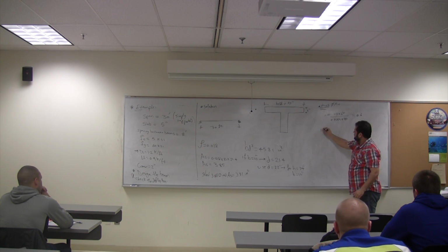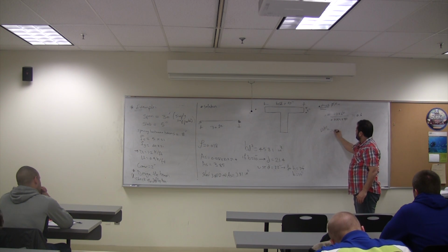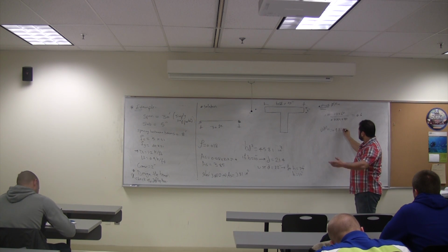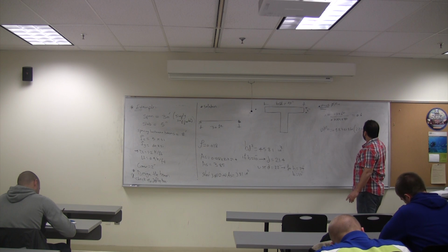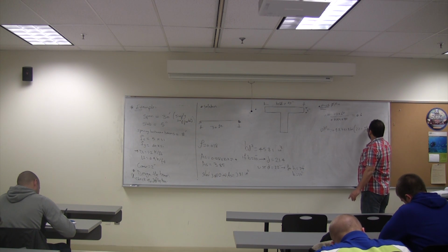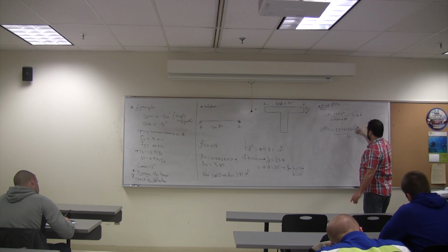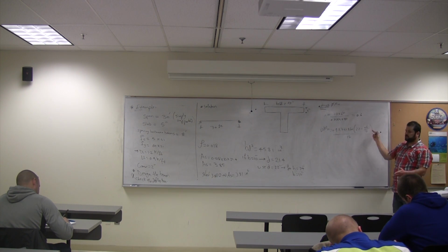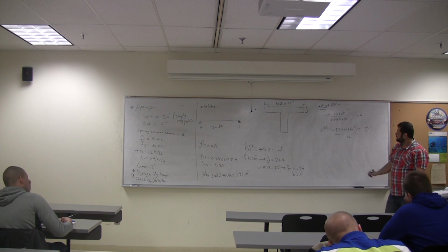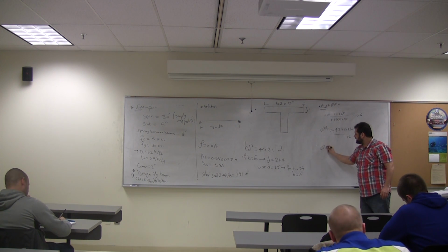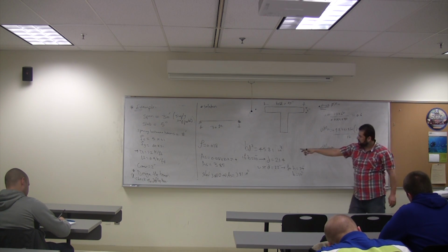So now phi Mn equals 0.9 times 3.81 times 60 times (22 minus 0.6 over 2). Everything is divided by 12 to change it, because this is in ksi, to change it to kip-foot. This is slightly bigger than 324.